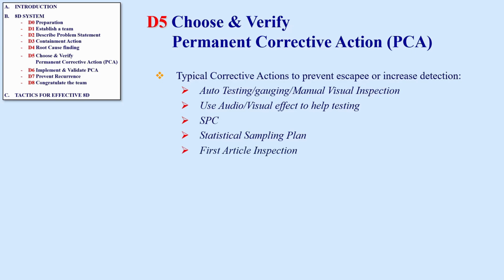First article inspection, also known as first piece inspection, is an approach to inspect the very first few pieces of production units in detail, before moving into mass production. As a minimum, we need to do this during the first NPI build. NPI stands for New Product Introduction. There are companies practicing first article inspection for every work order, or even every beginning of shift.